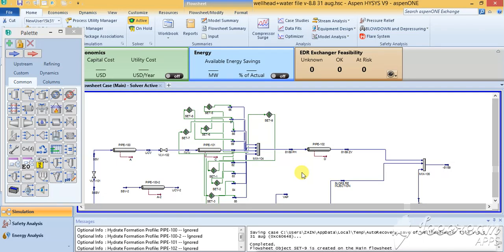Another important thing that I would like to discuss with you here is that once this simulation is generated, we generate a heat and material balance. Later on we define the PFD, we generate the PFD for a new system. This is the engineering cycle. Then we go for the P&IDs. Just before the P&IDs, we do a preliminary design of the P&IDs based on our control philosophy, putting in the PIs, TIs and all those things, instrumentation.